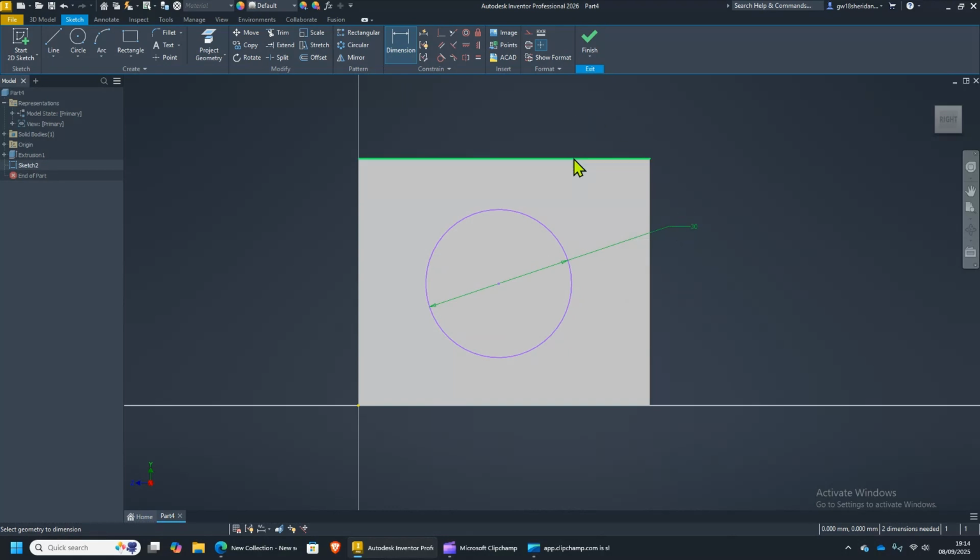So, to place this in the middle of the face, one way we could do it is with dimensions. If we know that the face is 60mm long, then I guess if we put a dimension between here and set it to 30, then we'll know that that is halfway along. And similarly, if we know that the height is 50, we can put a dimension in between there and the centre of the circle vertically and put that in as 25. Half of 50 and half of 60.